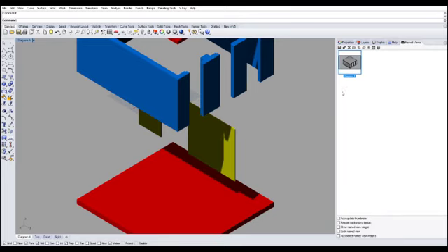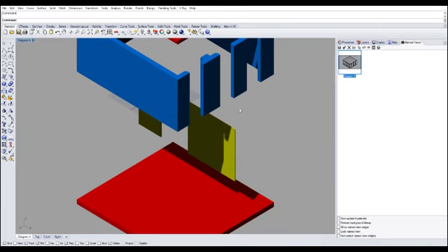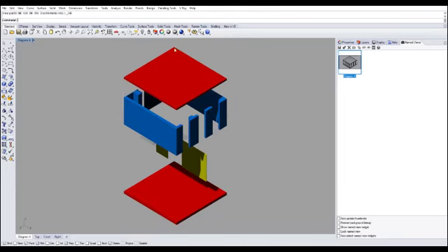Obviously, one thing that we do not want to do is sacrifice the view, as we want to keep consistency. So this view, if you recall, came from the isometric northeast view. If you click on that, it is still the isometric northeast view, same as our diagram A view, except this time it includes all of the components that we need to render for this particular render, which is the exploded axo. So I want you to go back to your set view, go to isometric northeast. Everything is nice and clear and visible.